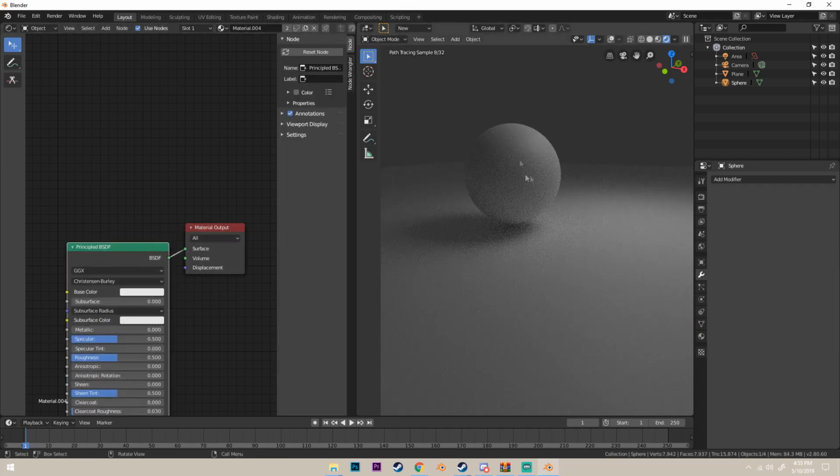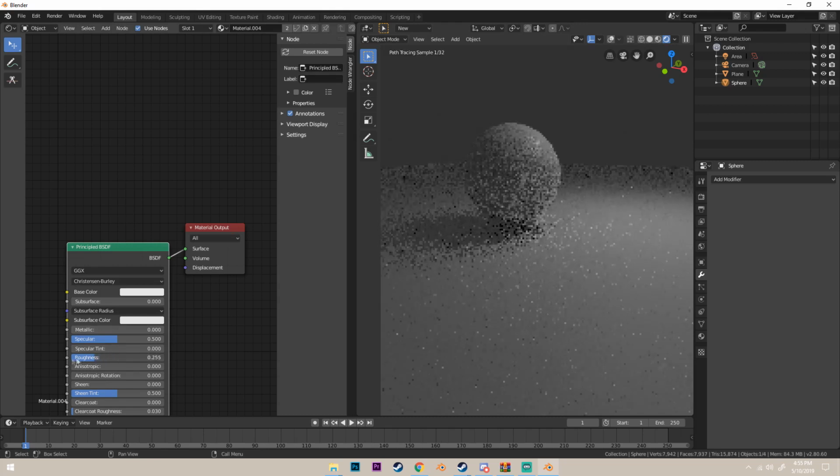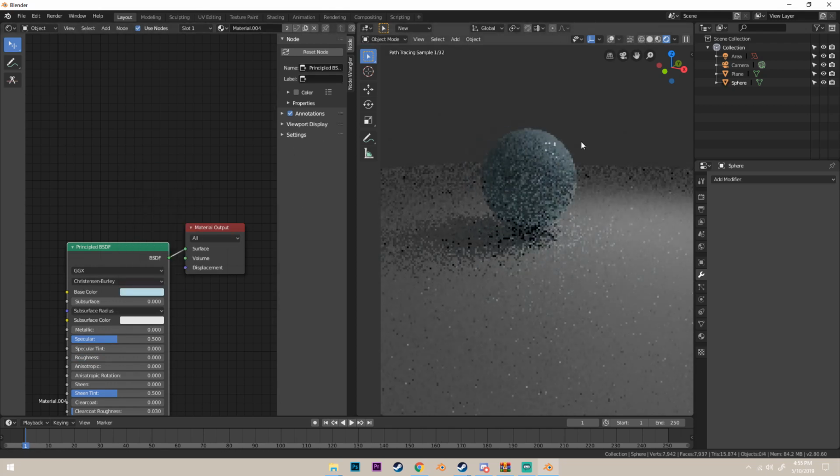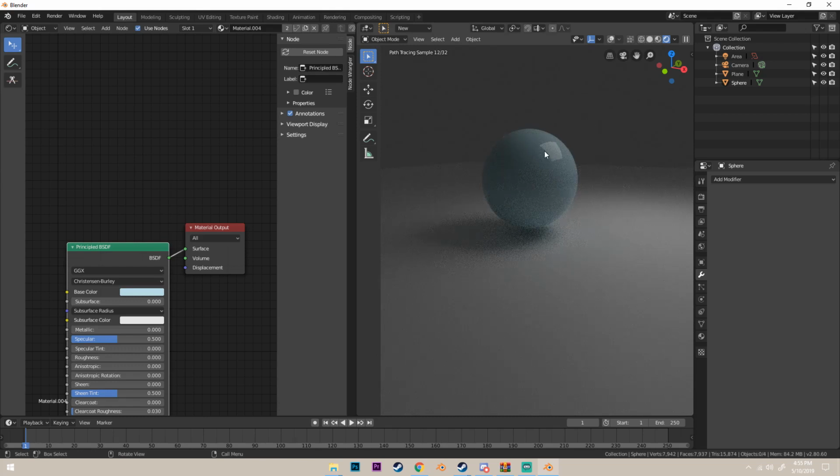And we give it this, right? We see that our ball is pretty cool. It's reacting to the light how it's supposed to and stuff. And if I turn roughness all the way down, you can see that now, and I'm actually going to change the color a little bit to show you more. You can see that now we have this reflection. And that's because we turned our roughness down. So you can kind of see better than using a cube how roughness affects the object. So if I turn this all the way up, it's completely rough. Turn it all the way down, it's that.